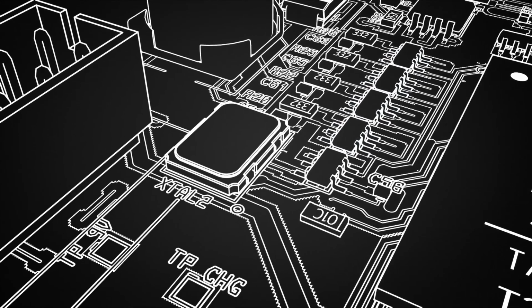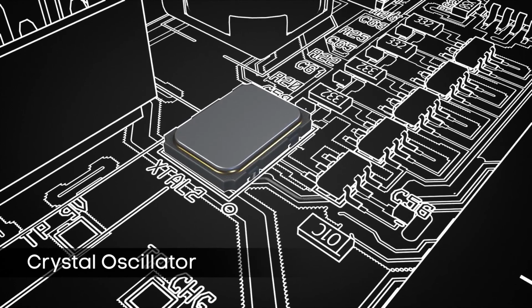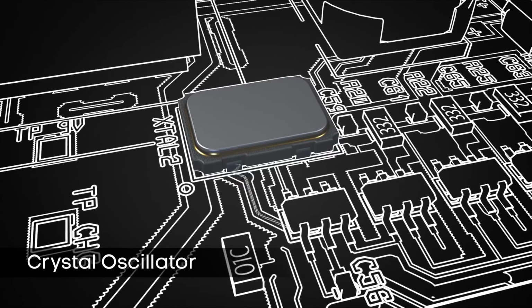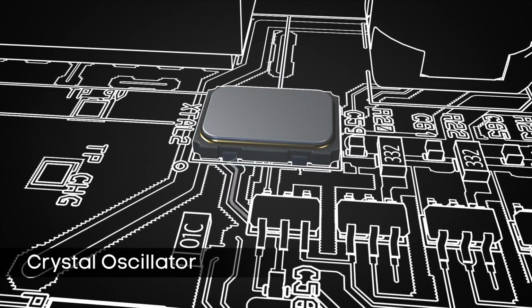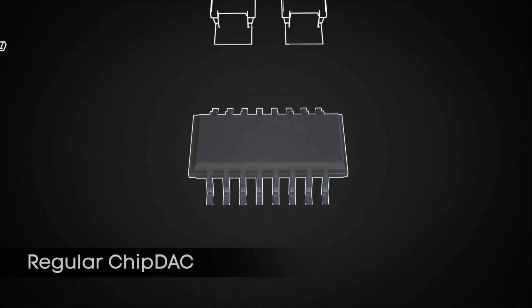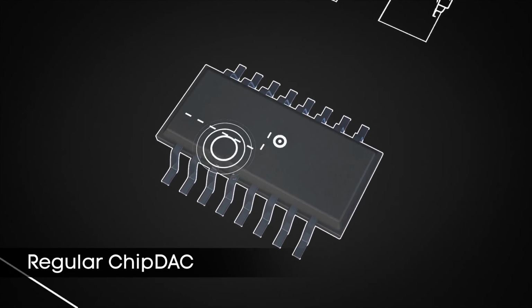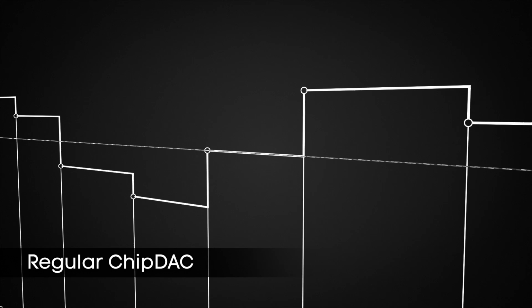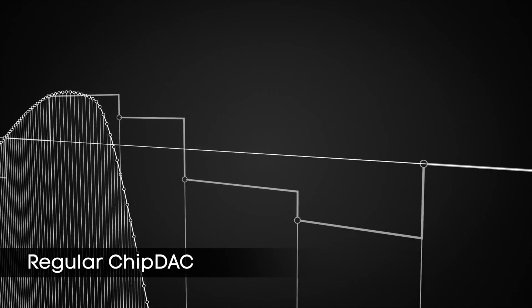Chord uses excellent crystal oscillators. These are the beating heart of the DAC, pulsing a voltage at fixed ultrafine intervals to send data. Jitter sound quality problems are eliminated partly because of the flip-flops having a direct or pure feed from the crystal oscillator. Regular chip DACs typically have an internal feed which succumbs to switching noise running through the silicon of the chip. These regular chip DACs typically operate at a frequency of only 6 MHz, giving poor resolution.